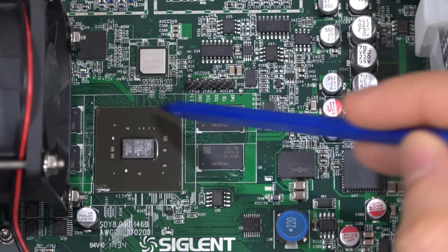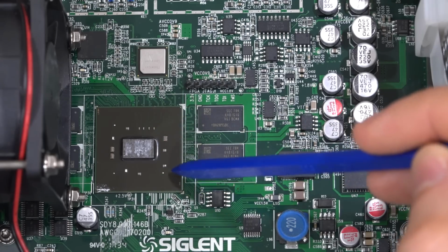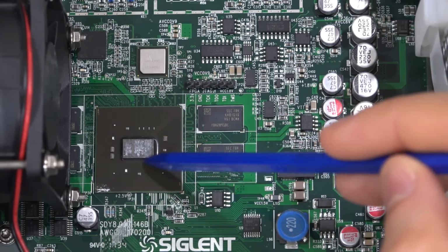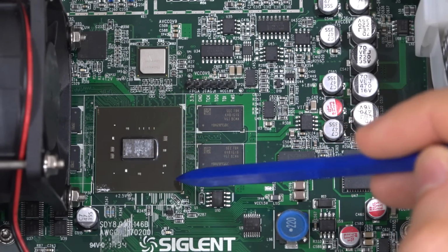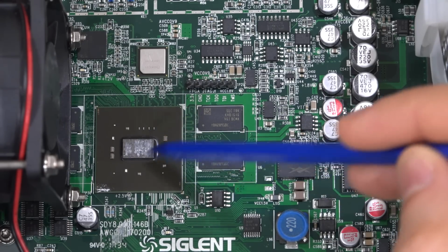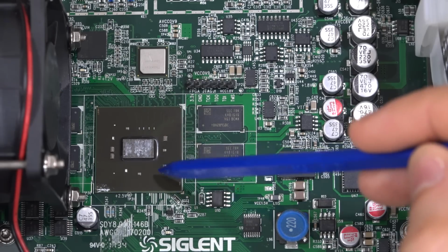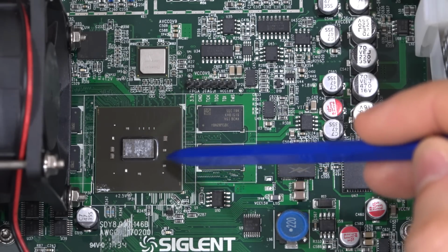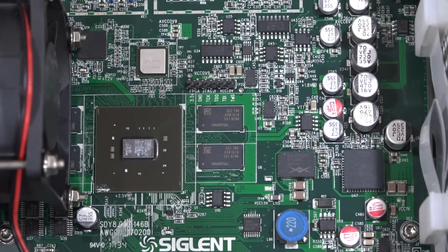I'm not sure what kind of FPGA this is. It's not a very large one, and there's no marking on it, which is a little bit surprising. I've taken the heatsink off of it. That's why you can see some thermal material directly at the back of the die. This is the back of the silicon that is exposed. It's flip chipped onto an interposer carrier, which then sits on the main PCB.